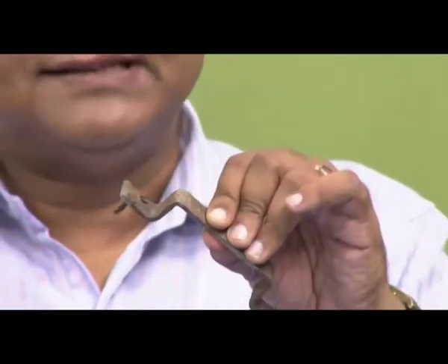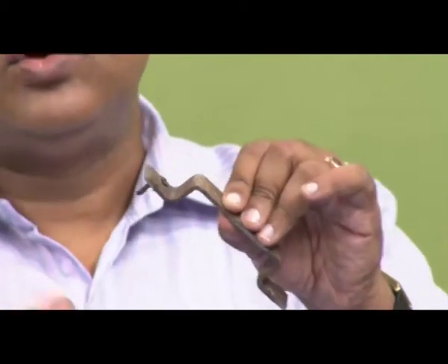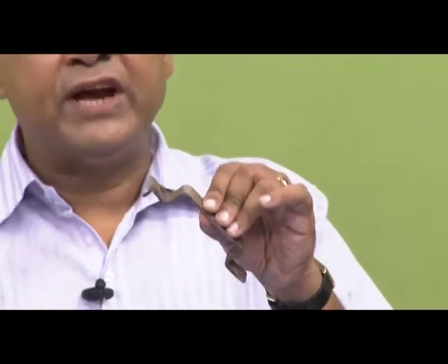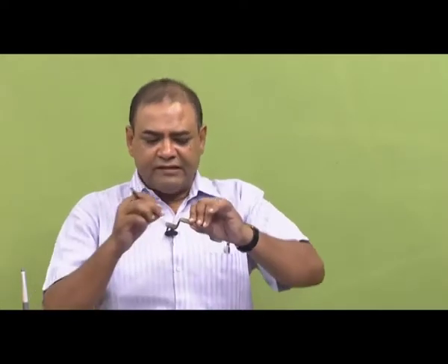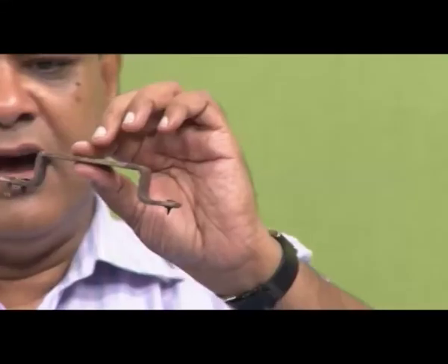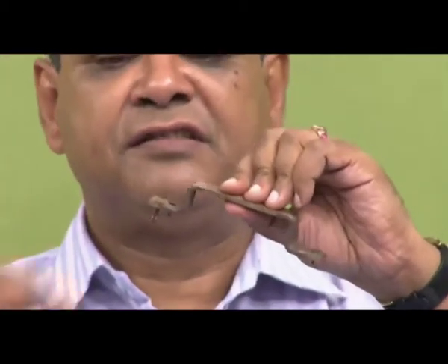That reaction would happen on this entire surface, but the bottom part where we do not have oxygen becomes my anode, and since iron dissolution, iron goes into iron ions, they are strong anodic reactions, those reactions would happen here. Then those iron ions that are forming will combine with the OH minus that are forming, and they form red rust or hydroxide or hydrated oxides of iron. So, this again can be explained from the point of concentration difference of oxygen. This is a classic example, you might also see such things happen at several locations.